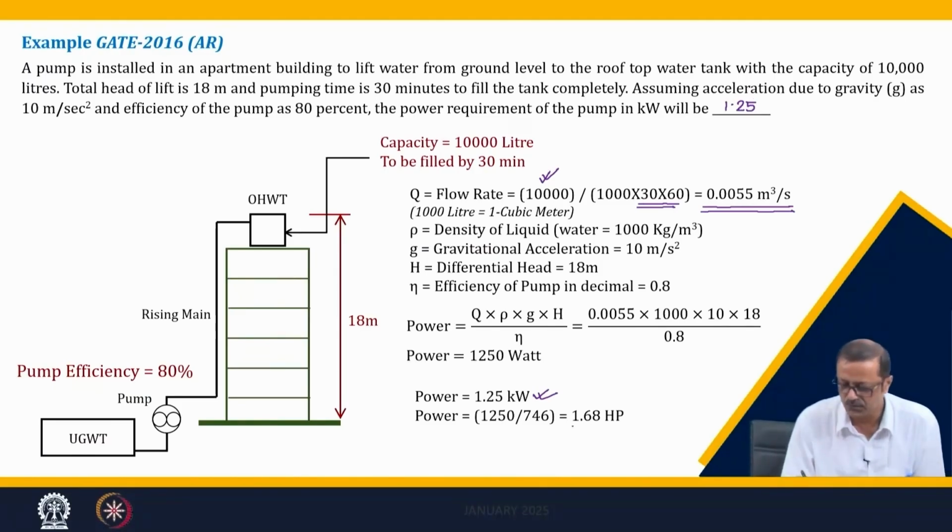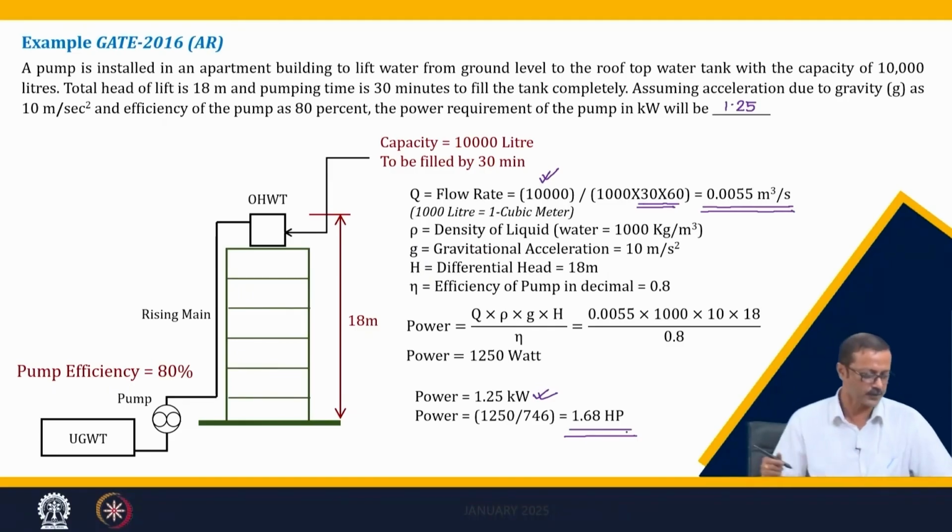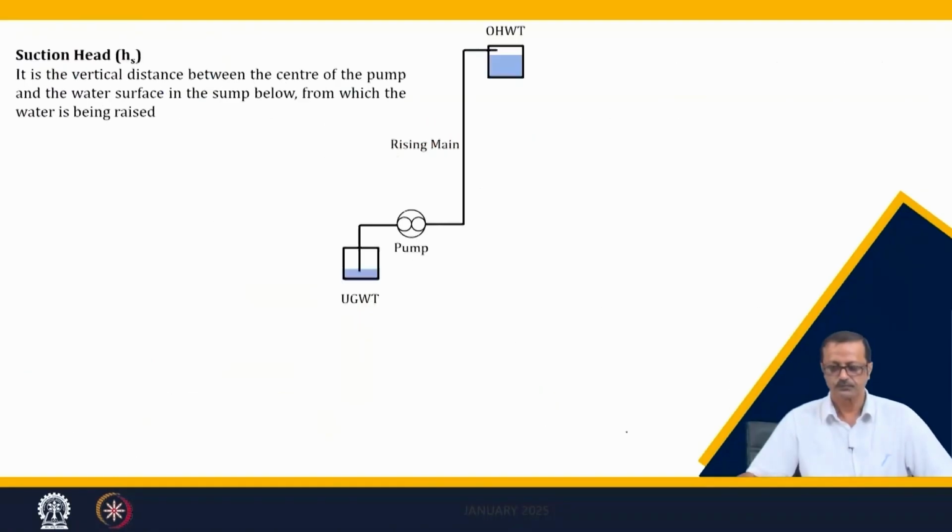So, sometimes the pump is rated with the horsepower. So, almost about 1.7 horsepower pump is required if I want to pump that particular water in 30 minutes.